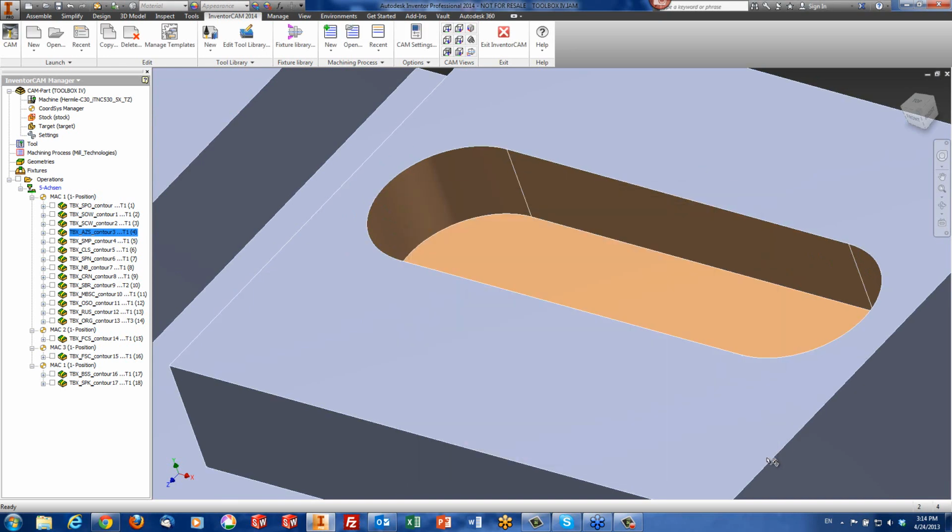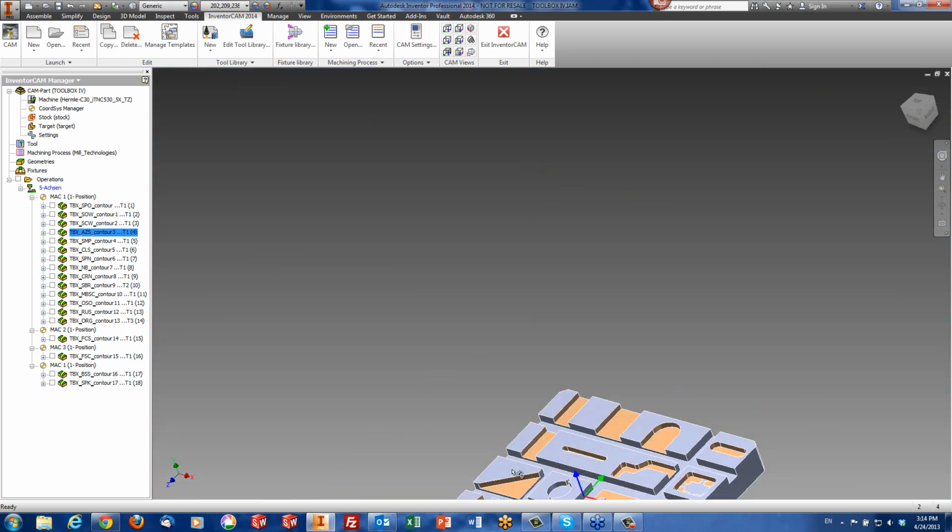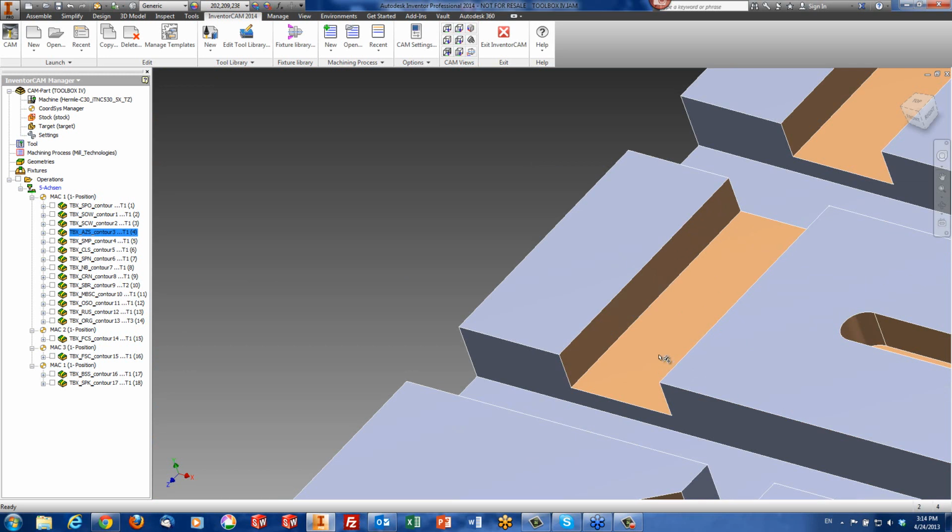Now, if I were to go into my next operation, it's really a simple slot. Many times what people want to do when they work on a simple slot like this is go across this wall over here. Then without going up, they want to go just a little past the part itself to the other side and then continue by going back across.